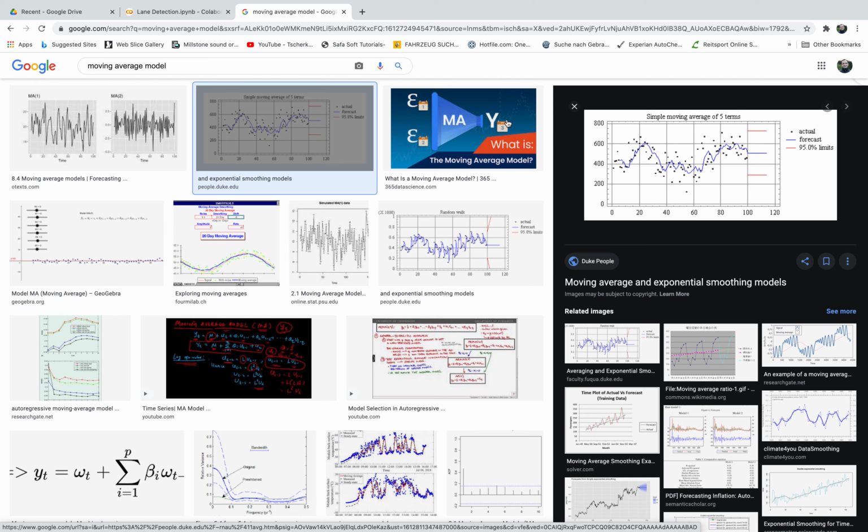Now, this is basically the moving average. There is a drawback that you need to consider, which is that this noise that you're trying to cancel could be a sharp turn that the car needs to take. A sharp turn would of course cause a sharp change of the coefficients because the curvature is sharply changing there.